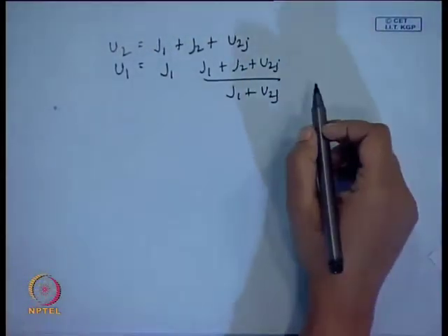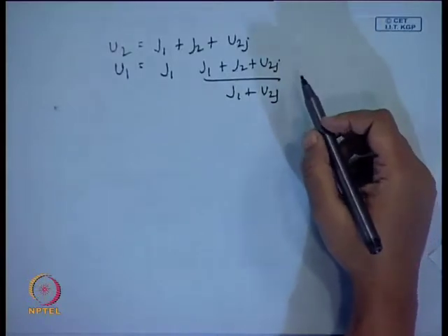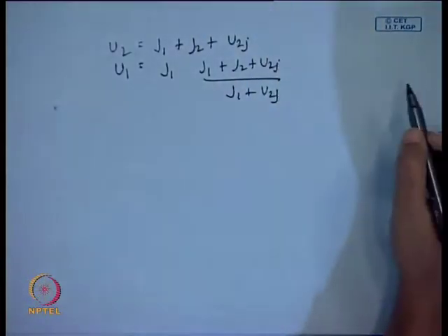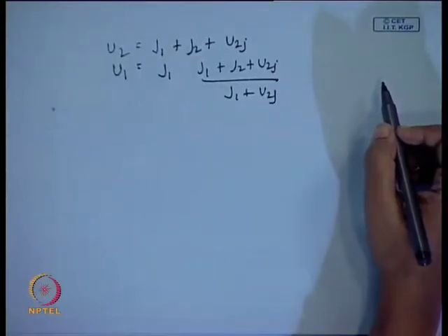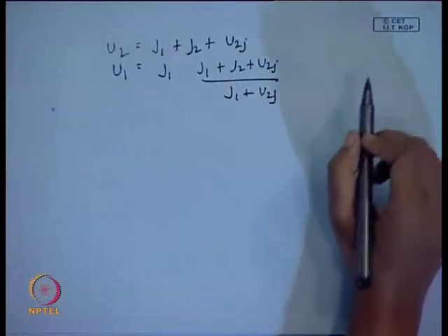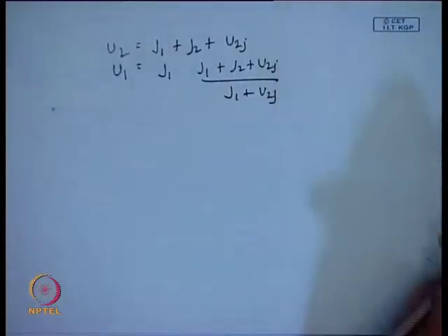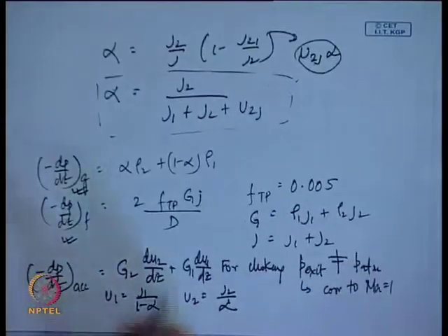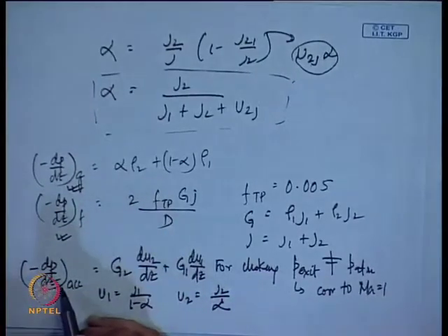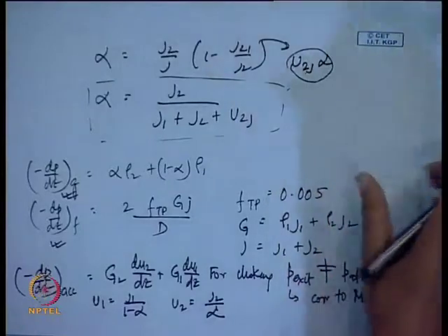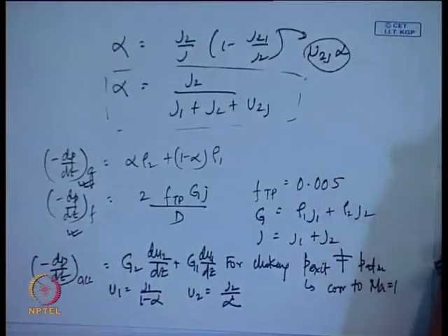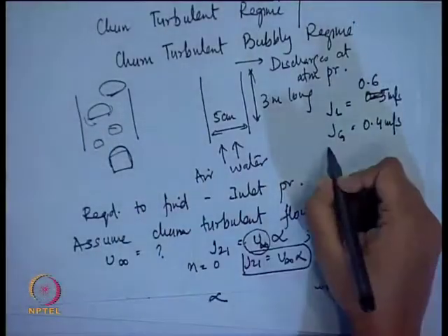Okay. Now, we find that since the pressure is changing along the pipe, what will change? J1 is not going to change, only J2 is going to change, is it not? So, just because of the J2 change there is going to be an acceleration pressure gradient in this particular case. Okay. Now, since there is no temperature change, I do not know whether I had given you the temperature, write down the temperature condition: it is around, say, 27 degrees centigrade.